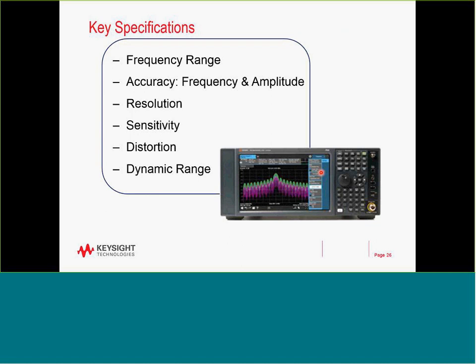That is the key point to direct you to the appropriate instrument. When people ask me which equipment they need to use, I ask them what their signal is, and there are a couple of questions about the noise level that you need, the phase noise that you need, and the frequency range, which guide you to the kind of equipment required to make a measurement. For frequency range, you want to be able to go all the way up to the harmonics of your signal or the spurious that you need to find out.